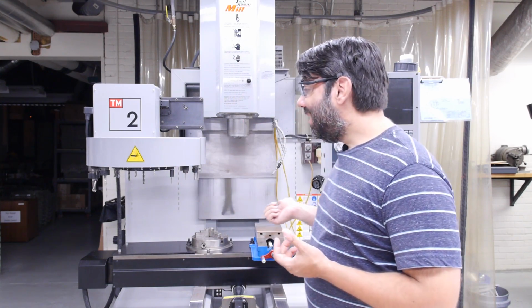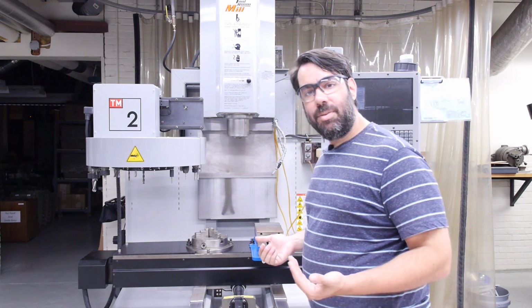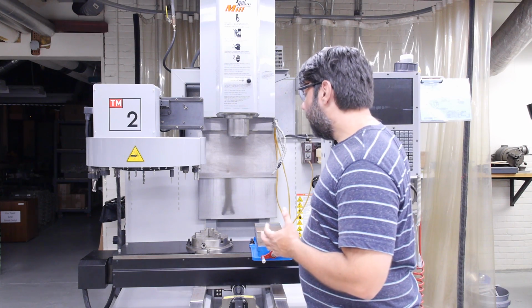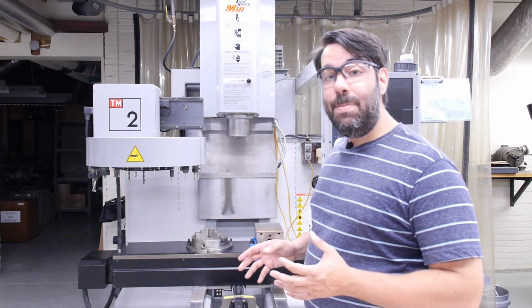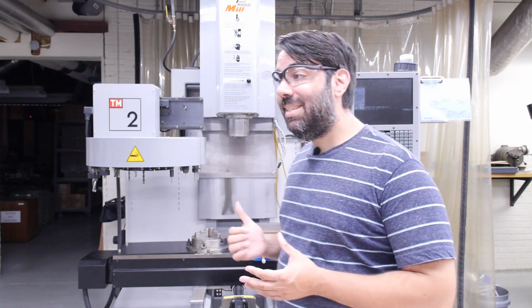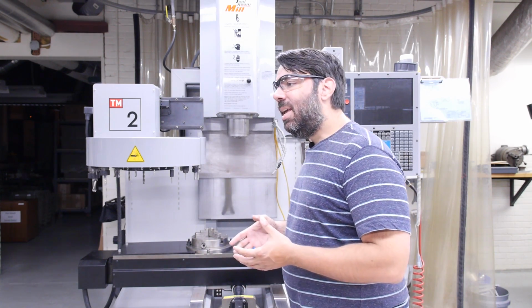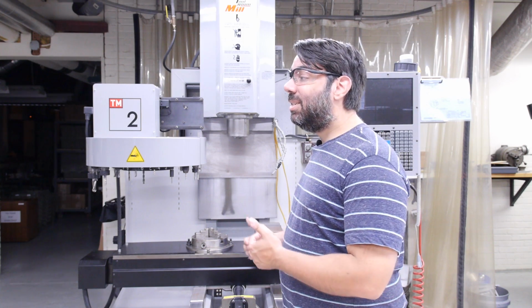A second disadvantage is the fact that to use a CNC machine, I need some extra skill sets. I need the ability to write a program and also need to be able to debug that program. I like to ask the students how many of them have taken a programming class with a show of hands. And usually they can tell me, or they will agree, that one of the first things you learn when trying to program is that it always requires debugging to get the program to do what you really intended for it to do. And it's no different on a CNC machine. Okay, so the second disadvantage is that we have to have a programming and debugging skill set in order to use the machine.